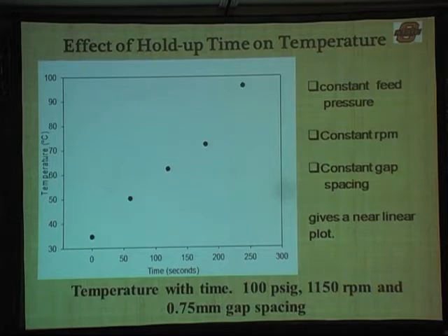The bottom line for this is normally we start off at room temperature. So it takes us about 4 minutes roughly to get up to the temperatures we need. Our goal was to get above 120 degrees C all the time. We can overshoot that, which gives us some operating flexibility. And in fact, once we get up to a sufficiently high temperature and then actually start the mass flow, we control the mass flow rate based on the outlet temperature. So we're ensured that we're leaving at a condition that can guarantee that we're sterilizing the material that's passing through the reactor.